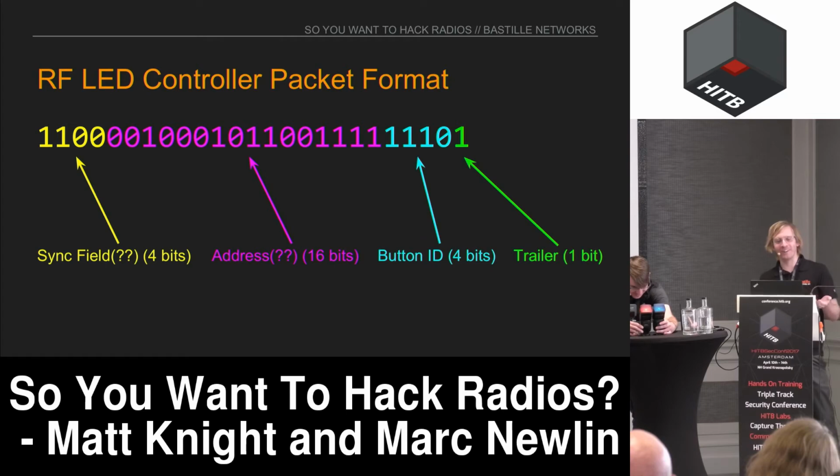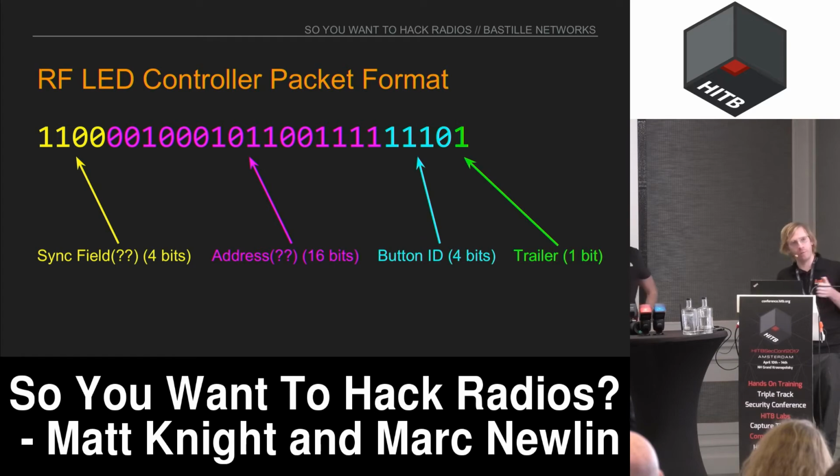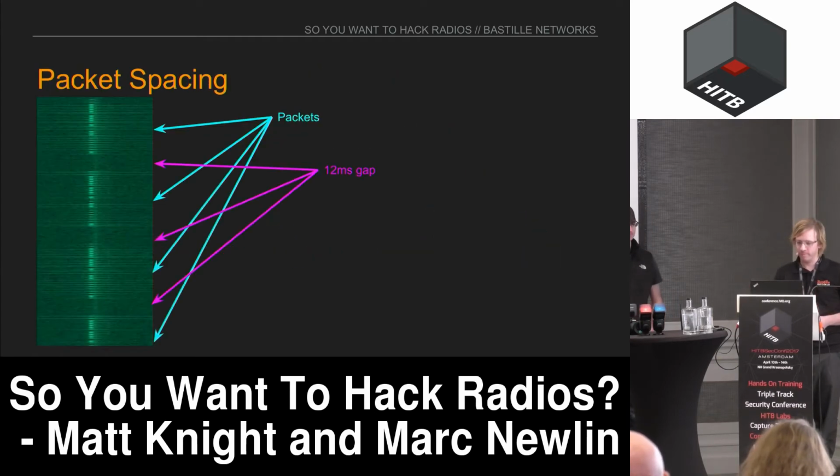So this is what our packet format looks like in bits for the LED controller. We have a sync field and an address. The length of each is unknown, but we can assume these for the moment. Then we have a 4-bit ID for the actual button on the remote, and then this 1-bit trailer.